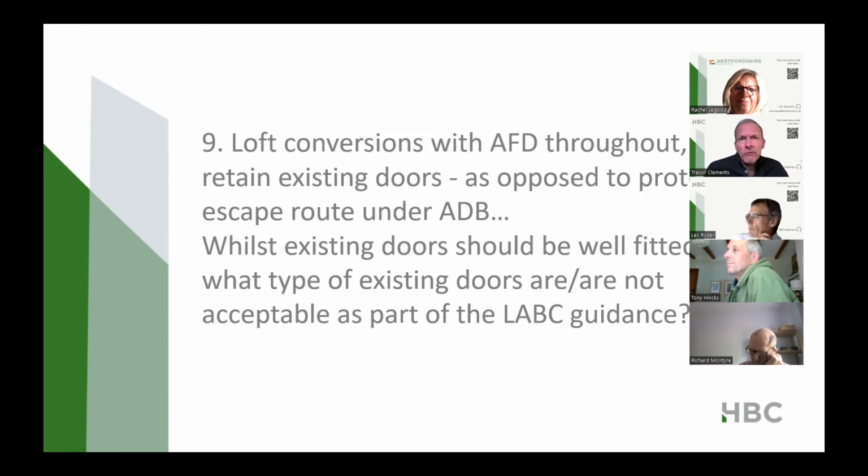A bit of a Ronnie Corbett. I've got to give you the background to that. Where did that come from? You won't find that in an approved document. Well, in 2010, we had a publication called the CPA, the Construction Products Association Loft Conversion Guide, and it introduced this idea of what they called the fire engineered solution. Option 4 in that guide for fire safety in a loft conversion was to have a type A or type B AFD system to compensate for the lack of fire doors.